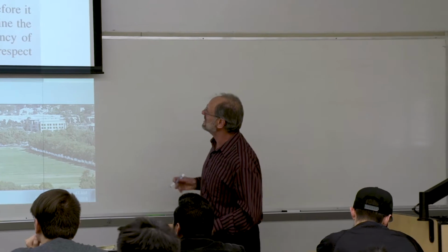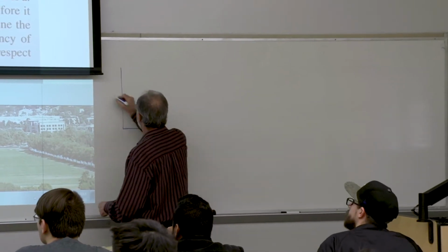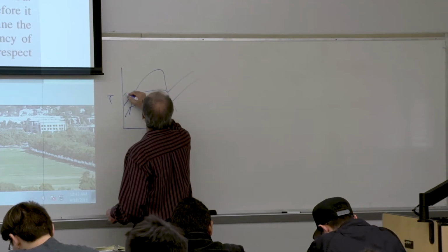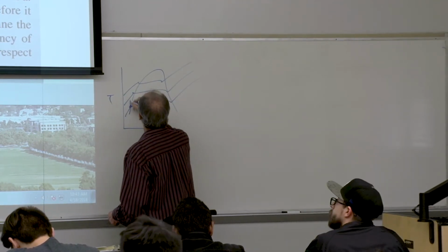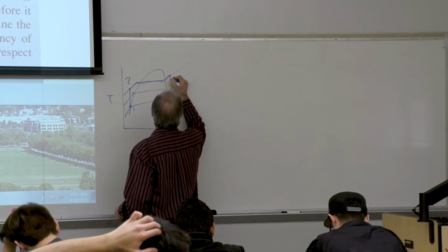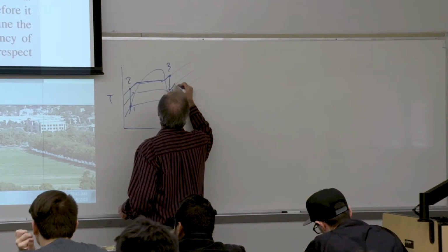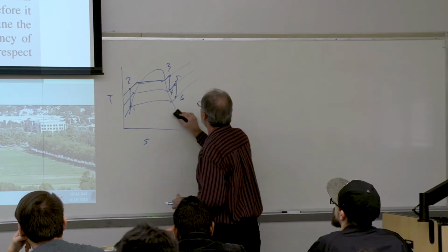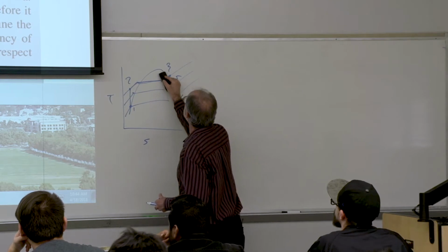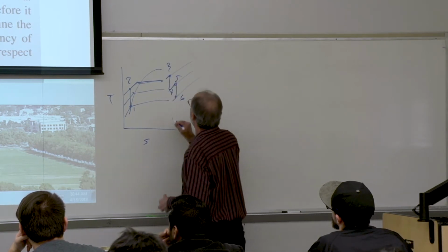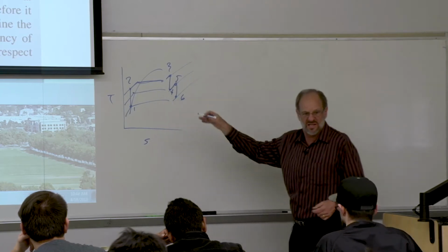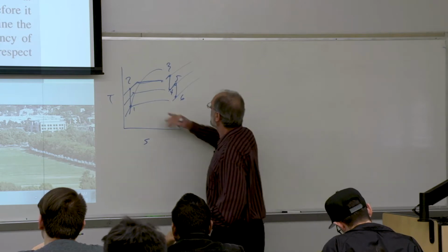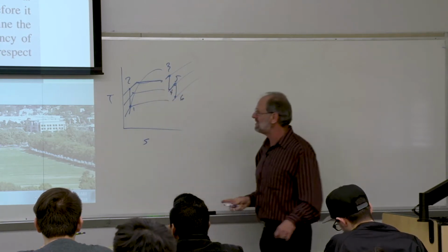All right, so let's just indicate what we have. Maybe I'll just do a quick T-s diagram relative to the appropriate lines. So 1, 2, 3, 4, 5, and 6. I'm not really sure exactly what my thermodynamic state is leaving the turbines, so often I would just leave off the right-hand side of the saturation lines until we're at the end and then see what's what. By the way, these lines should be horizontal. I clearly didn't do a very good job.